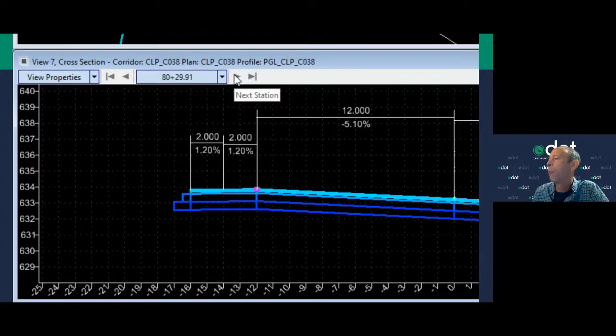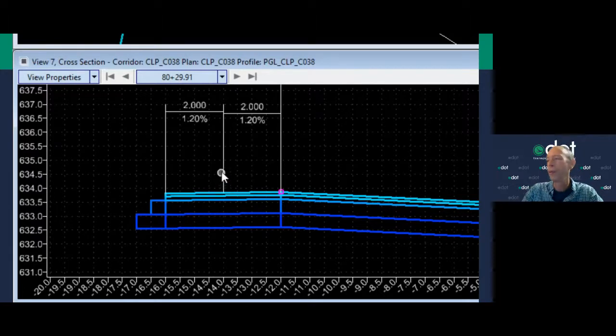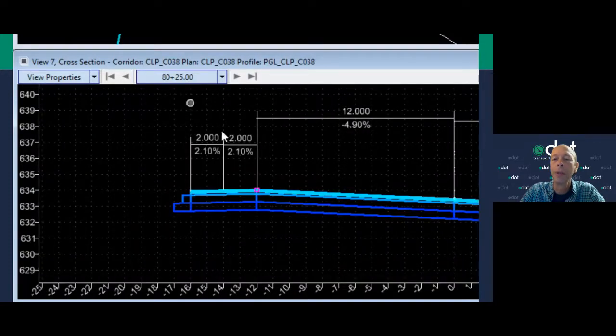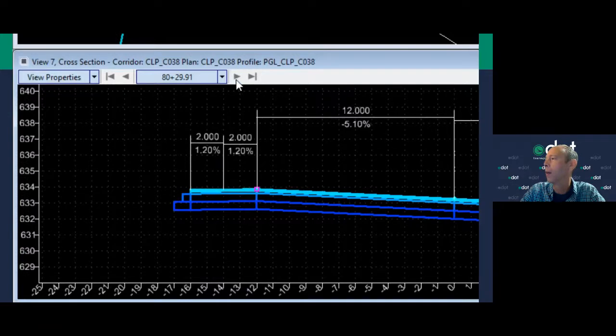Here I am at 5.1, and what I would expect to see is a negative 1.9 over here. Instead I'm seeing a 1.2. That's because we're in this transition area between 5% and 6%, and it started to bring that center point up as part of the transition defined in our rollovers. That's what the user ran into and said, hey, this isn't correct. It should be a 7% maximum break. I should have the minus 1.9 here. So that's the problem that was encountered.